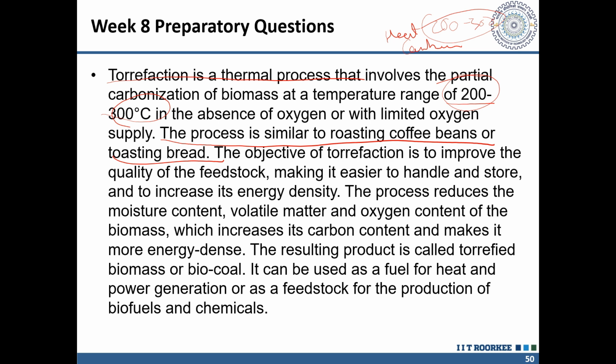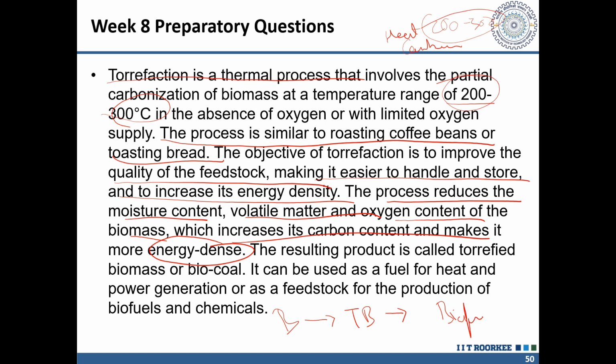The objective of torrefaction is to improve the quality of the feedstock, making it easier to handle and increasing the energy density. Before processing this biomass, we first purify it in order to increase the quality. This process reduces the moisture content, volatile matter, and oxygen content of the biomass, and increases the carbon content and makes it more energy dense. The resulting product is torrefied biomass, which is very high quality, and this can be a feedstock for biofuels in order to get a high yield of biofuels.